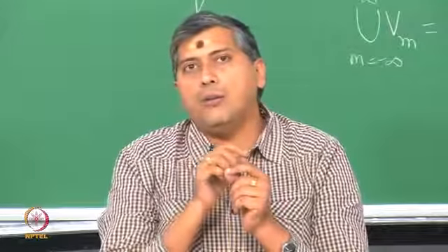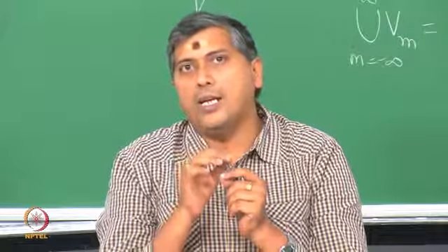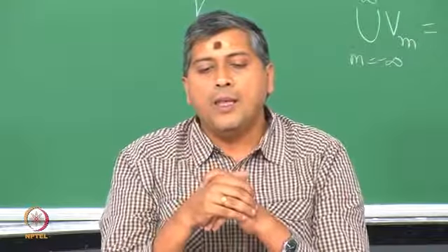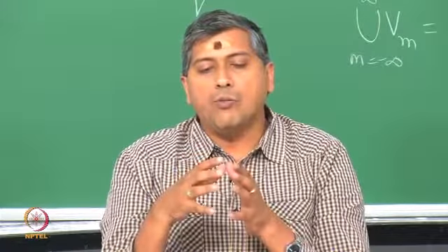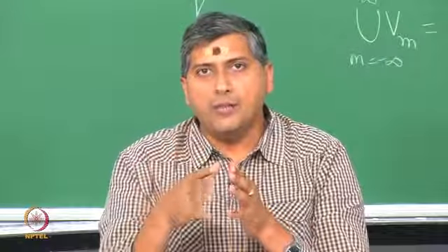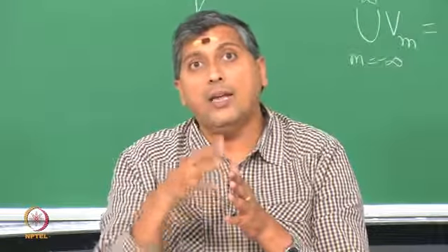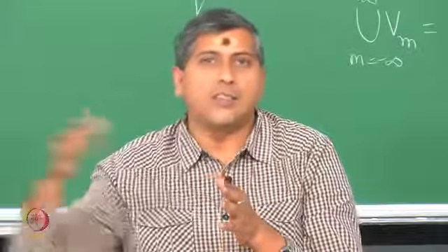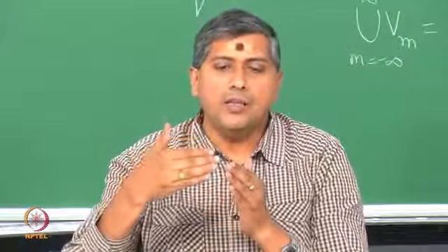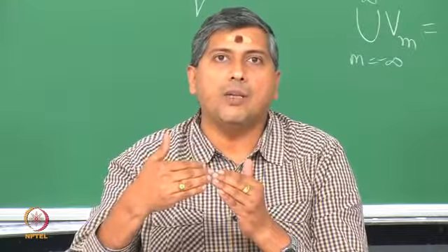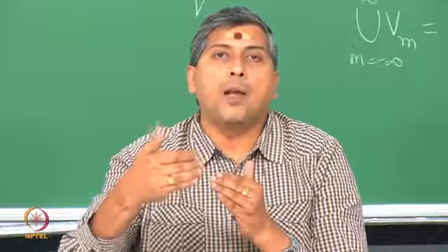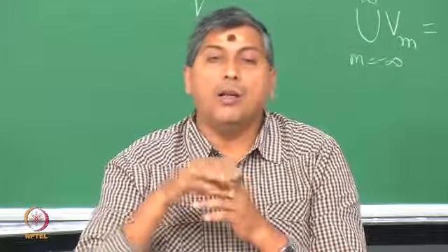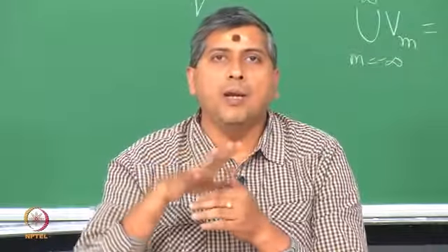And if you recall, the way we are computing the dyadic DWT and then the orthogonal DWT, basically what we are doing is we are evaluating CWT at specific scales and also translating at specific translations only, right. That is, we are translating in such a way that we generate non-overlapping basis functions, and that results in minimal representation.